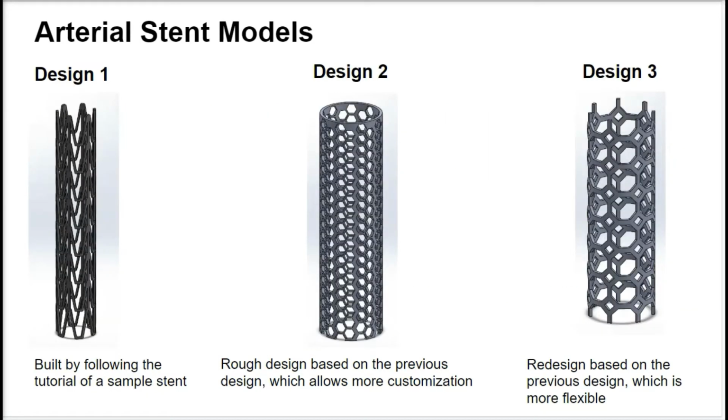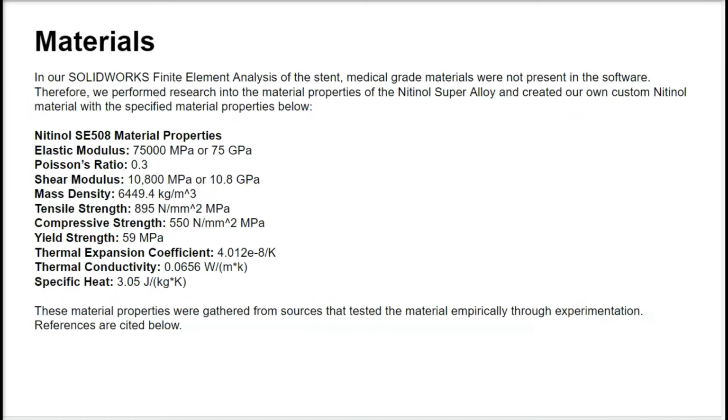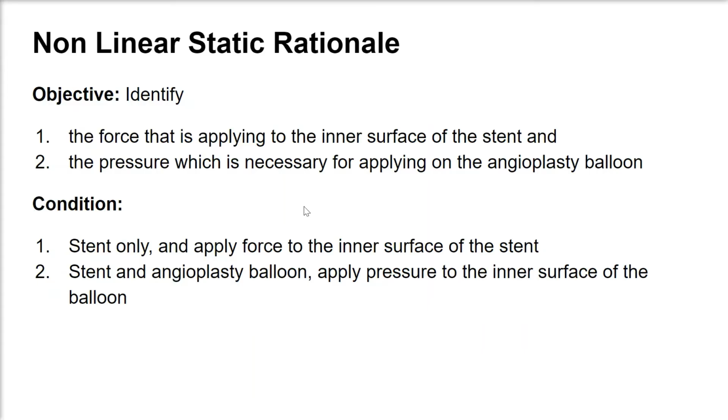Here we have 3 different CAD models that we developed with other model additions in our tests for testing different anatomical conditions. For the material, we apply medical grade nitinol. This is unavailable as a default in SOLIDWORKS, but we did research about the material properties and inputted it as a custom material. Thank you, Kevin.